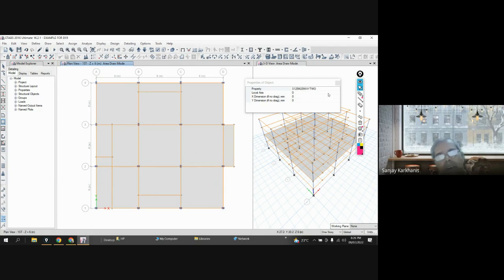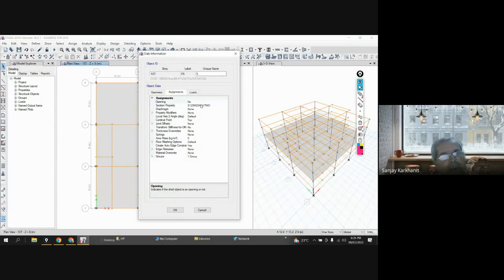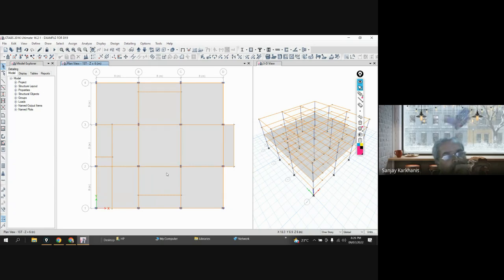But now see what has happened. You have created every slab as a two-way. You can see M20 S125 M20 way 2. So every slab is a two-way slab. Now you say that, sir, this is my one way, this is one way, this is one way, this is one way, this is one way. Okay, you may say that this is two way, that I agree. But if I click on this, you can see the entire slab right from this point to this point is drawn.